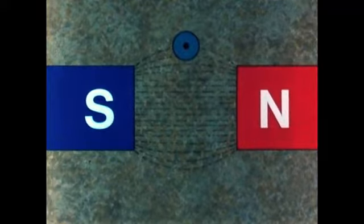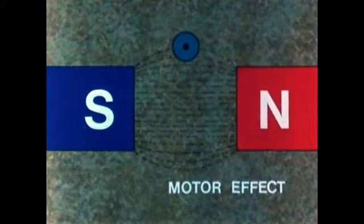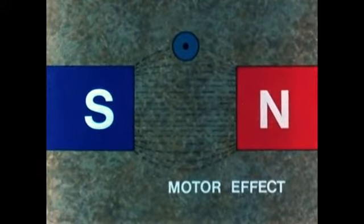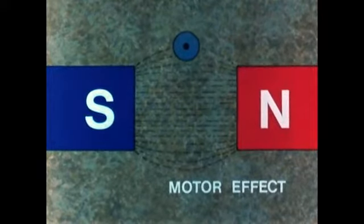We had a magnetic field with the wire going through it at right angles. When a current was passed through the wire, it moved to cut across the lines of force. This is called the motor effect and is the basis of all electric motors. We need to be able to predict which way the wire will move.